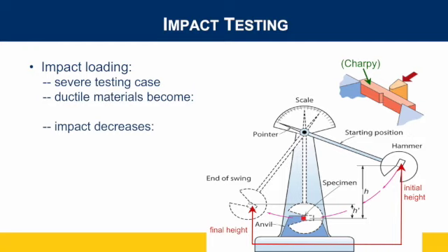Okay, so let's go into impact testing. So we see how a material can be improved so that it doesn't fail under normal loading. But impact is another form of energy transfer that can make very ductile and very tough materials actually look like they're brittle. So impact just means force over a very small time frame. Materials act differently if you pull on something very slowly, and it bends and just kind of stays that way, versus if I hit it really hard with a hammer, you're going to get a different response. Okay.